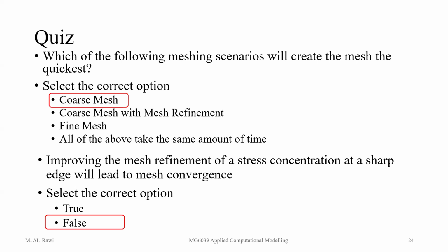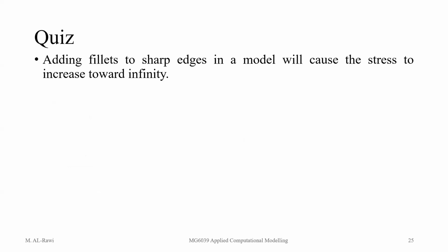We cannot even control it. The last question, adding fillets to sharp edges in a model will cause the stress to increase towards infinity. True or false? False. Because fillets, the opposite, they actually make it more stable and get to the true result.